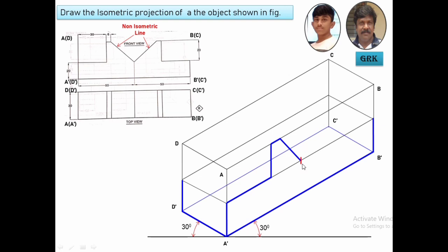Now I can go in this direction itself, up like this. Otherwise I can come from the other side. Since already I got the plane here, let me measure the distance from here to here, which is once again 30 mm since it is symmetrical. So mark it here on the other side. Then measure this vertical height, plot that vertical height in the front face.